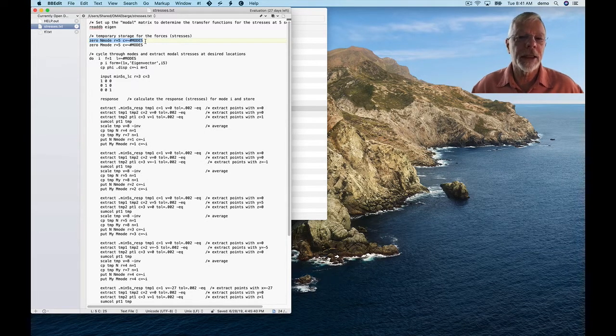But in any event, for our case, the P over A, remember N, the capital N, is the plate variable, which is force per unit length. So what we need to do to get stress from that is just divide by the thickness. And that gives us the average cross-section stress on that cross-section. But in any event, I'm using 5 points here. I've decided I'm going to do it at 5 points.